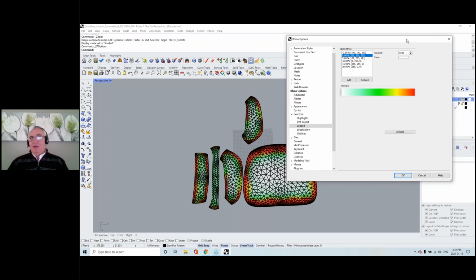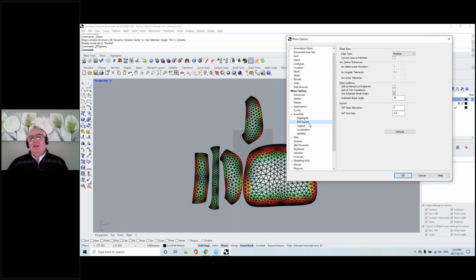And we want to take all the stress or strain out of the material, so when we sew it back into the 3D shape, we're not having spots where the fabric will be ripping apart, which would not be good. The other thing is, if I go to my DXF export, this is where I put my seam allowance, and the headrest is in metric, it's in millimeters.